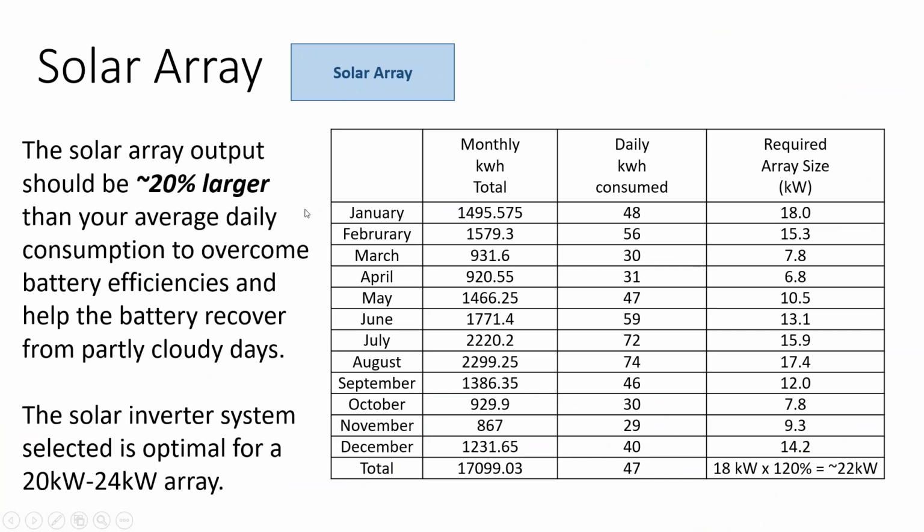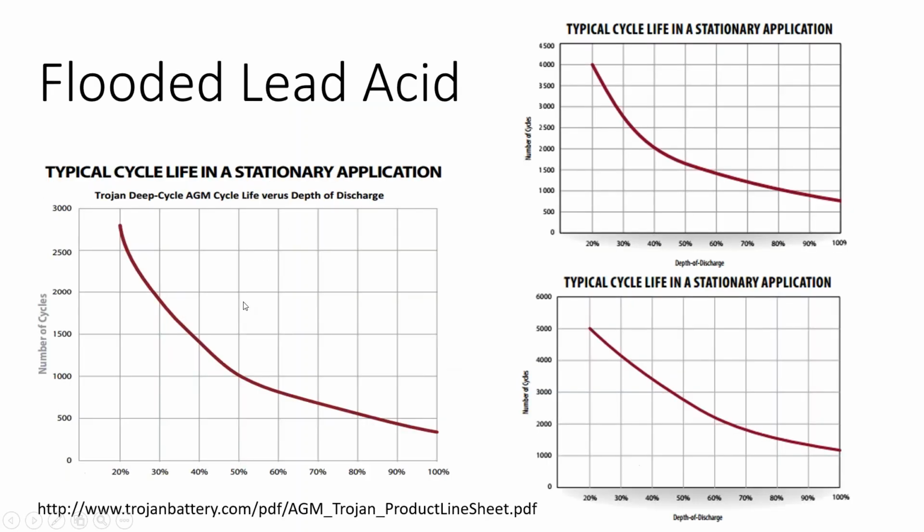So with PV Watts and your monthly bill, you can start to make a stab at your battery bank size. But we do need to understand how to read our battery bank spec sheet for that. What's interesting to me about these spec sheets is that they're all for flooded lead acid. These are for different tiers of flooded lead acid, and they aren't the golf cart batteries.